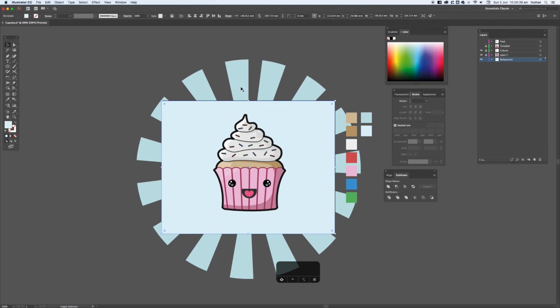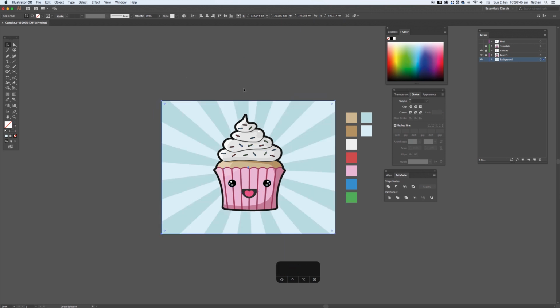And with the rectangle still selected, I'm going to Alt-click on the strokes you just made to select those as well, and then I'm going to hit Command and 7, and this is the shortcut for a mask. And that's going to mask off everything outside the rectangle you just made. I'll go on to explain masks in more detail in another video, but for now, just marvel at your new creation.